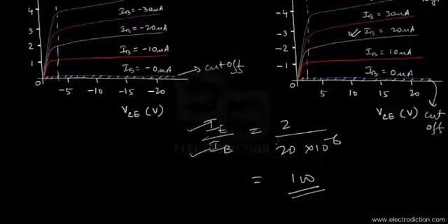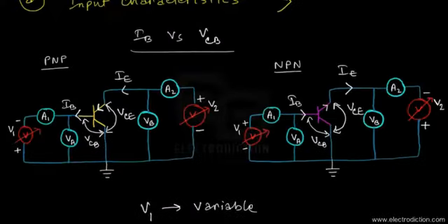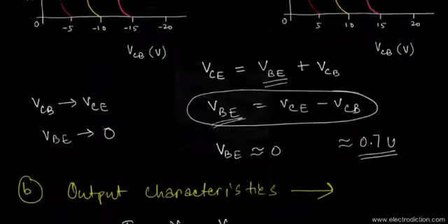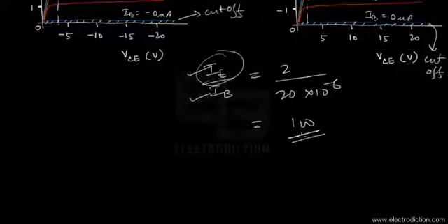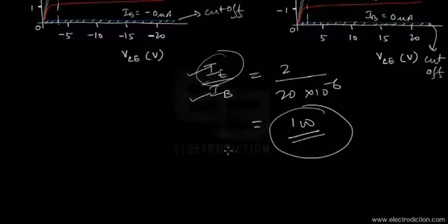So this mode of operation does give us some gain in the magnitude of the output current received from the emitter terminal. This factor is expressed by the term gamma, known as the current multiplication factor for the CC mode.